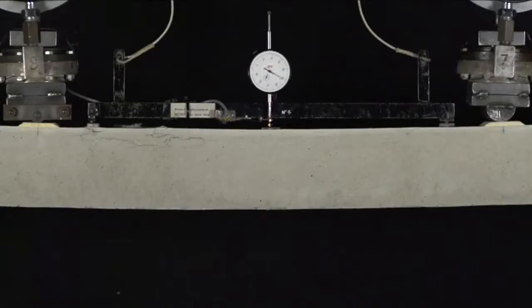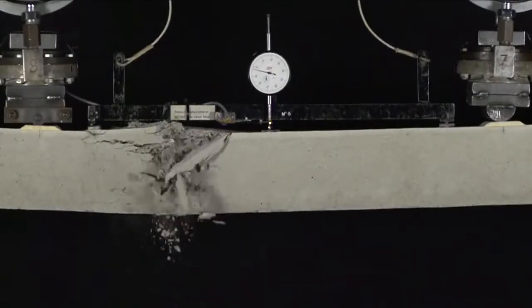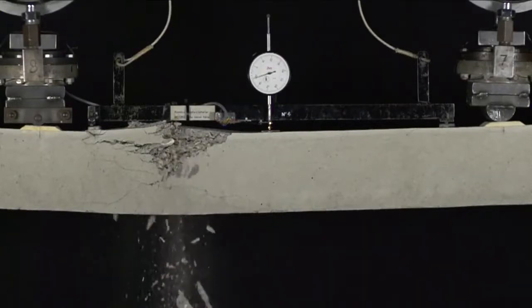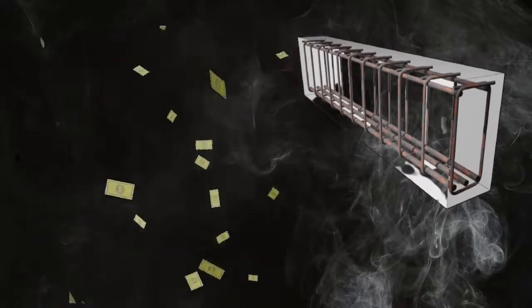Therefore, no warning or sign of failure is going to occur, and we know that concrete is very weak in tension but good in compression. This type of section is not advised for beams because not only will it have a brittle failure, it will also increase the cost of construction due to the higher percentage of reinforcement placed in the beam.